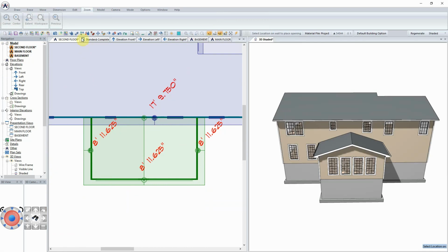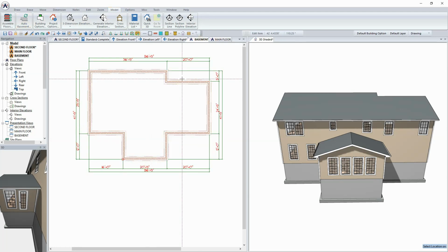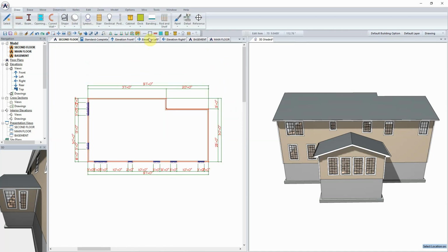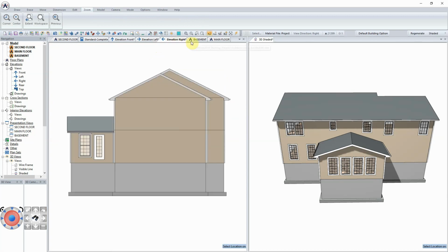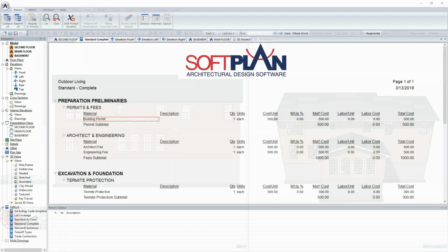And so, in conclusion, for today's first chapter or module, we have created a main floor plan using the existing wall types. We have modified the openings after we place them for their exterior trim and whether they were included in the Softlist. Using the model and auto basement, we quickly created a basement plan, and then through File and Save As, we have created this second floor plan on the actual drawing. This gives us elevations to work from automatically as we design it, plus the three-dimensional model.